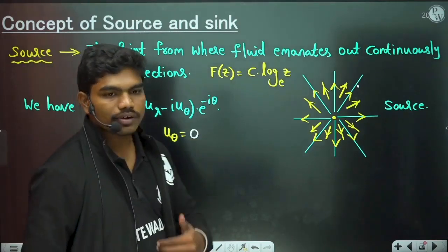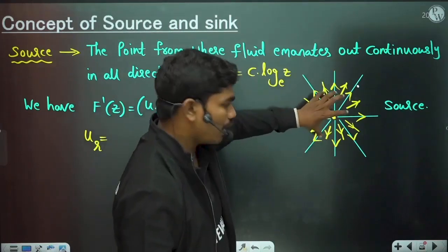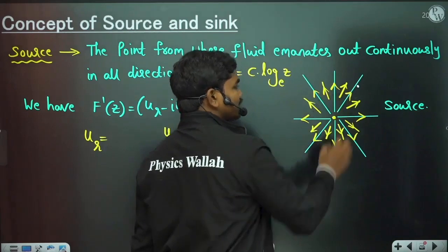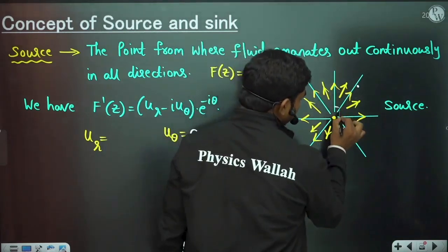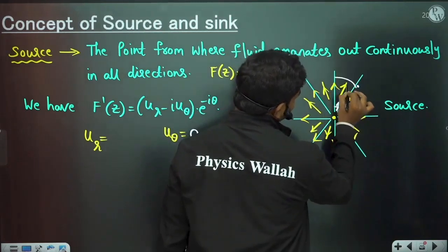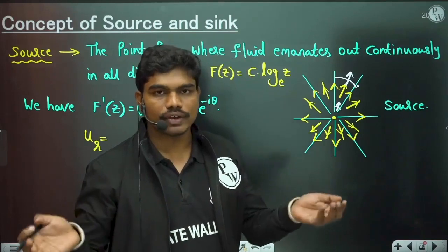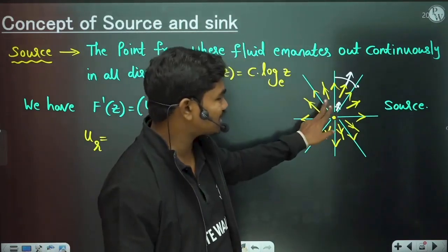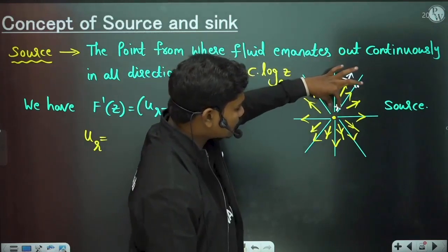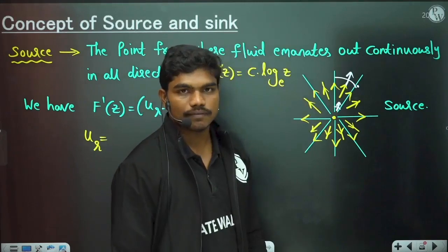Next, what about the radial velocity? Please try to understand this. Let us suppose some discharge came out. The same discharge should travel between these two streamlines, because obviously flow cannot enter or cross the streamlines, so the discharge between the streamlines is constant. At this location, where the flow area is very small, there is some velocity for the fluid particles.